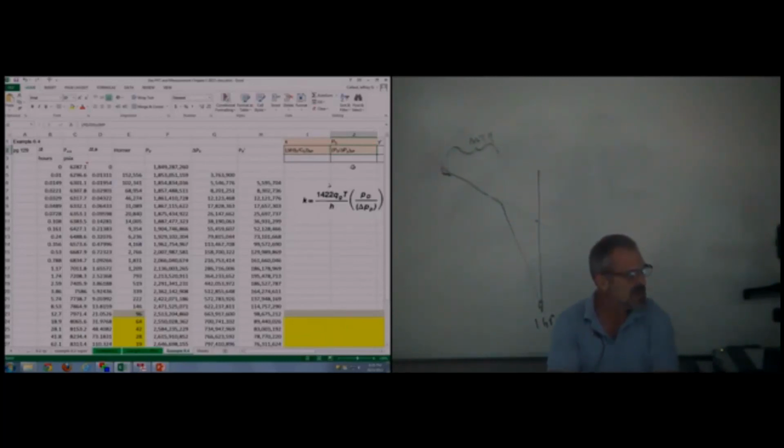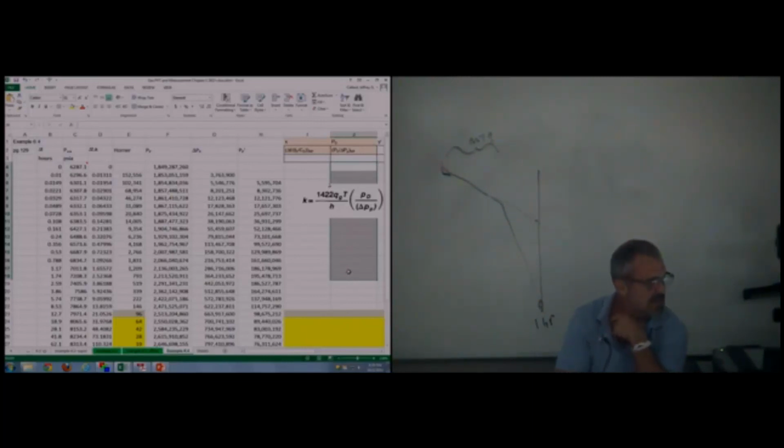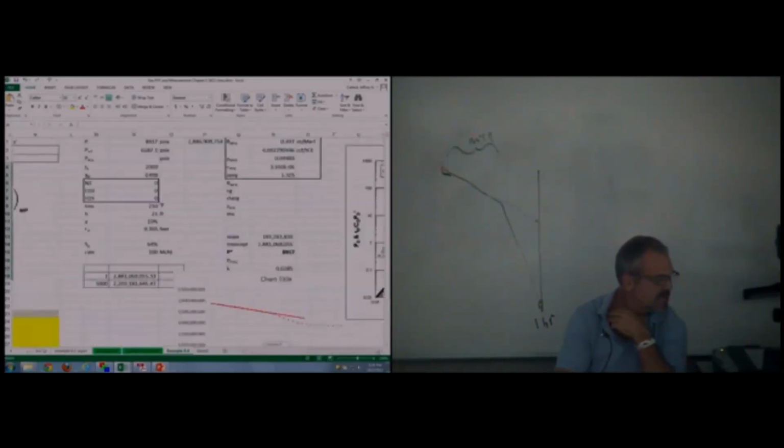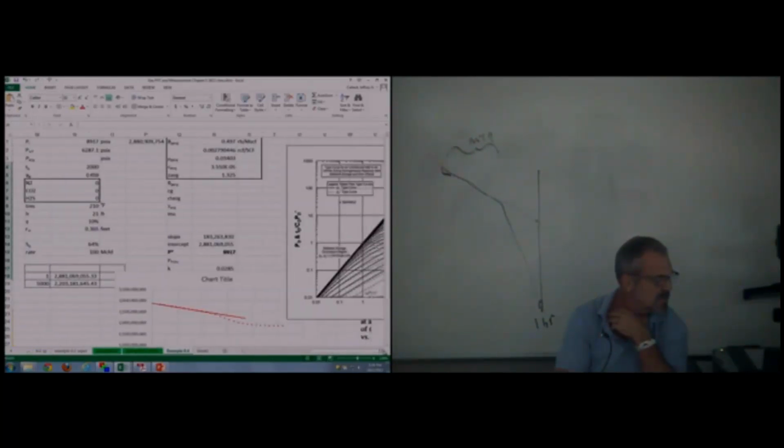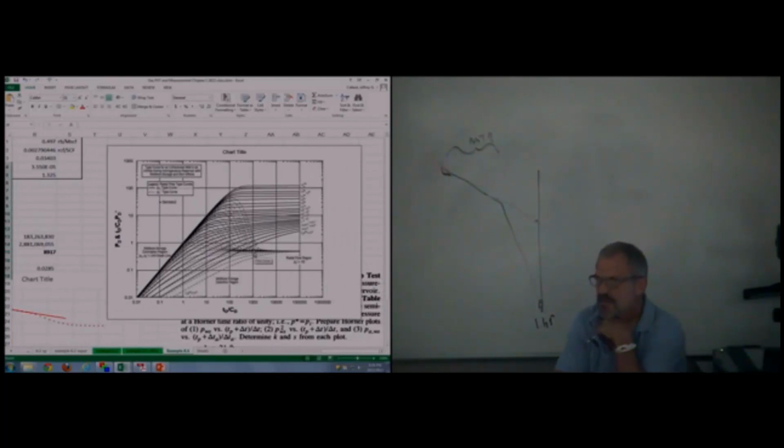You have the wherewithal to at least get this column. We haven't done wellbore storage. I'm not going to go into it in the next 20 minutes, so we're going to stop there. But you have the wherewithal to calculate the J column. That's half the data you need to put yourself on a type curve. And then we'll put ourselves on this type curve, then we can see if we pick the right data. Okay, we'll stop there.